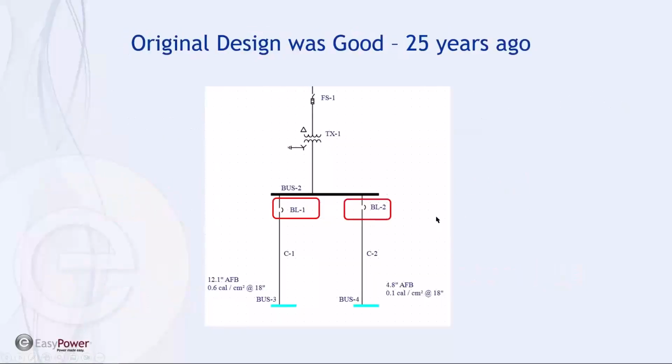Now, 25 years ago, a design like that, like he described, was perfectly fine because arc flash wasn't something that was taken into account. The problem was that we had fuse protection, or the overcurrent protection, on the primary side, and the current that was being measured at the arc was not being extinguished fast enough to prevent arc flash hazard or arc flash damage. So today, the solution would be to properly size protective devices for each of the loads on the secondary side.